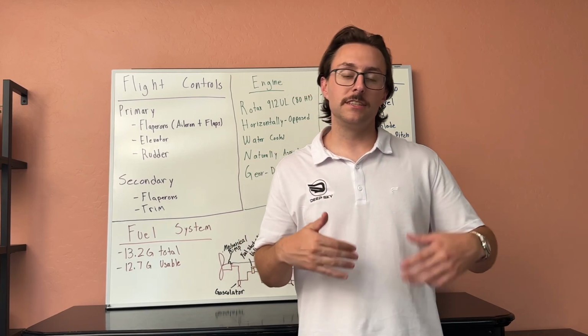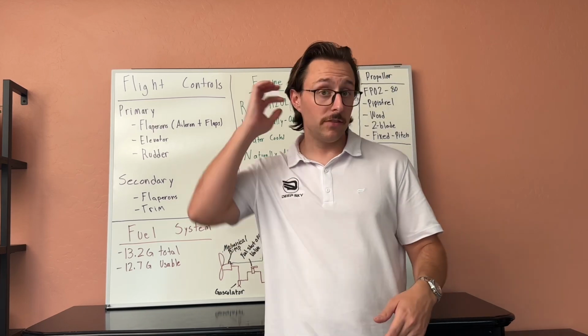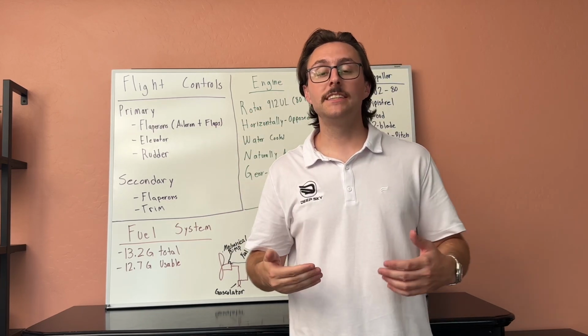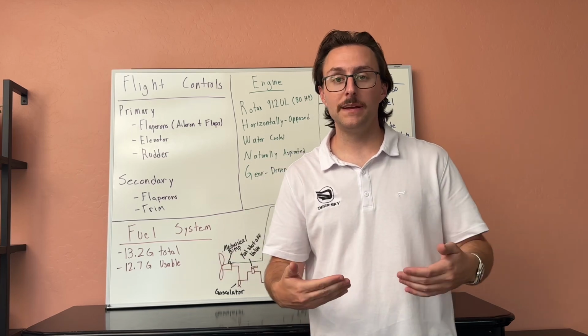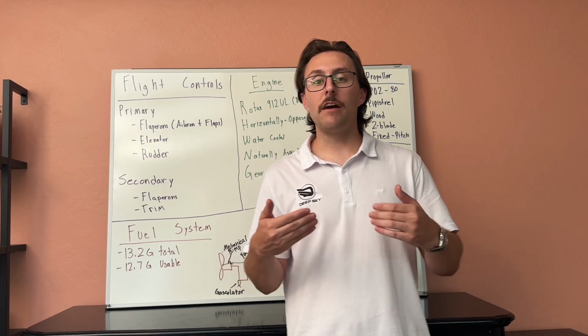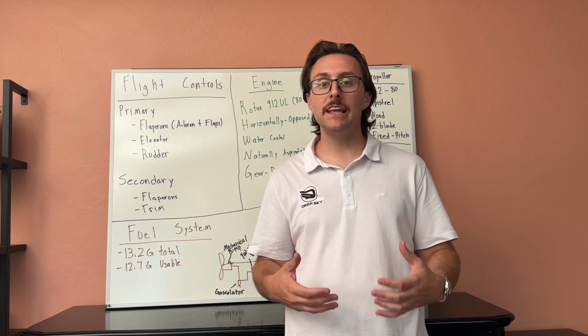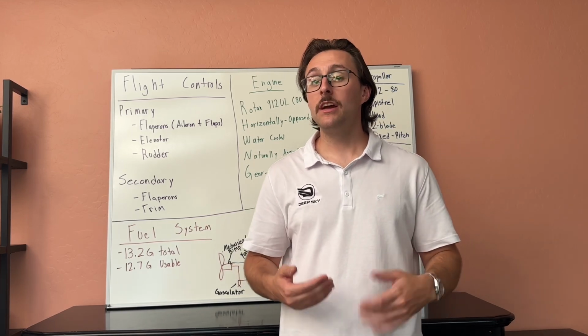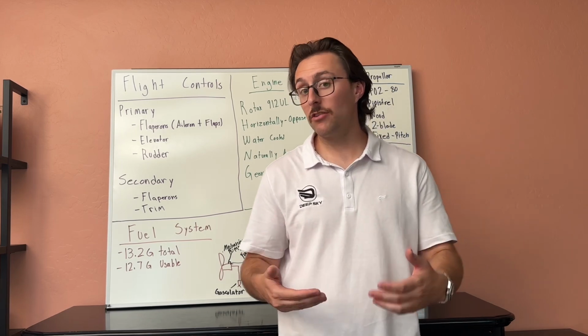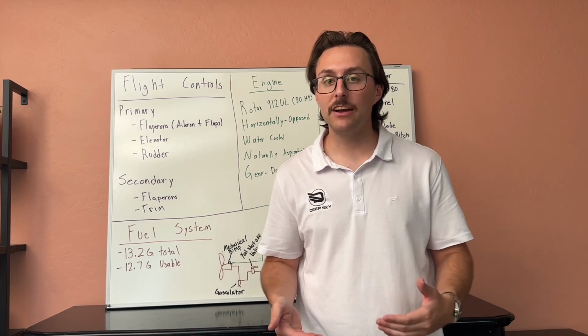Secondary flight controls. This is going to be your flaps. What do these do? Well, these are devices that create lift. So as you pull your flaps, you can now go at a slower speed and still not stall the aircraft because you are now generating more lift. We will get into another time as to why those generate more lift, but what you need to know for now is just that they generate more lift. They're considered a secondary flight control.